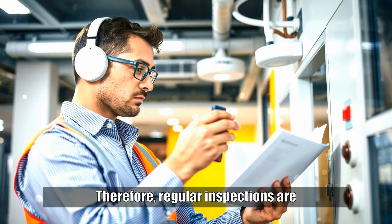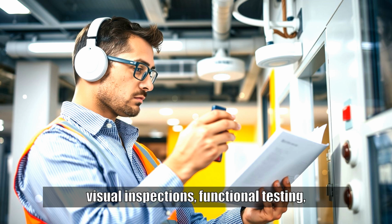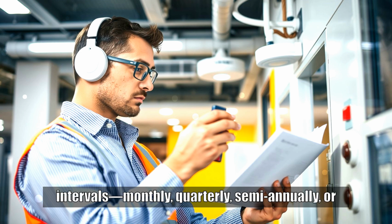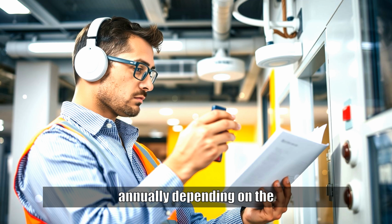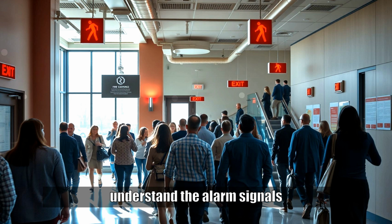Therefore, regular inspections are mandated under fire codes and standards such as NFPA 72, which recommend visual inspections, functional testing, and documentation at specified intervals: monthly, quarterly, semi-annually, or annually depending on the system component. Fire drills and alarm response exercises further ensure that the building occupants understand the alarm signals and evacuation procedures, enhancing the real-life effectiveness of the system.